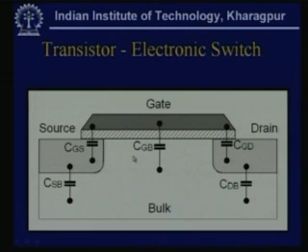How can this act as a switch? If the base is high, means a 5-volt supply is applied at the base, this makes the connection. So, the path is on, that means current will flow. So, simply, if the base is high, it will be connected, and if the base is low, that means 0 volt, it will disconnect. Now, this concept we can apply here.